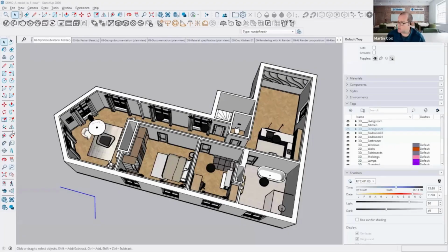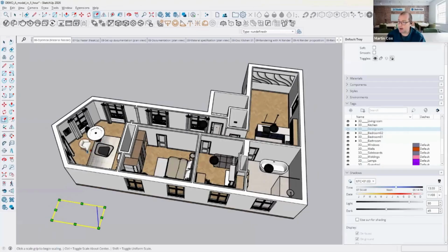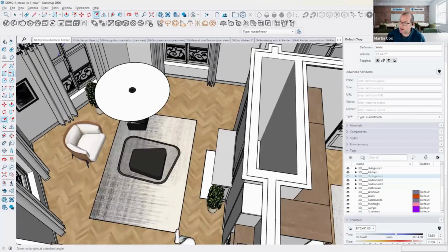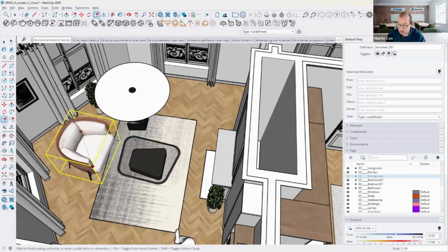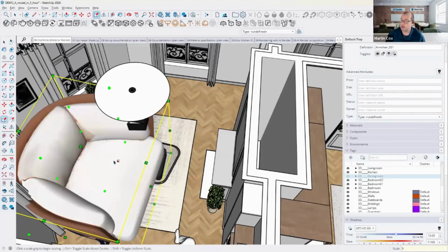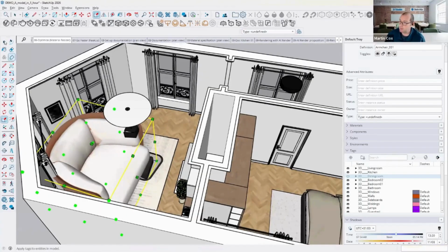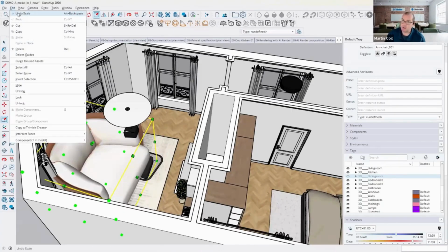How to change the dimensions of those dynamic objects? Scale. Using the scale tool there, that will scale any particular object. Depending on what size the chair is there, if I choose scale and choose the corner, which means it's a uniform scale, and again, down the bottom right-hand side, you can see what scale I want to add. If I say I want a scale of 3, that will make it 3 times the size. Every gaming room dream, that chair. But yeah, let's undo that scale.